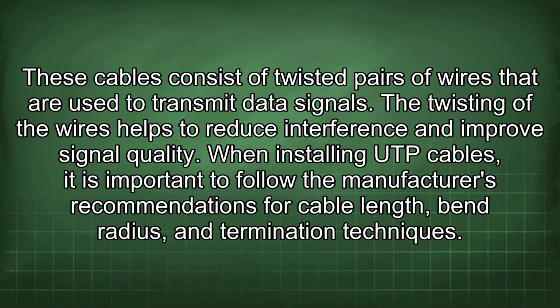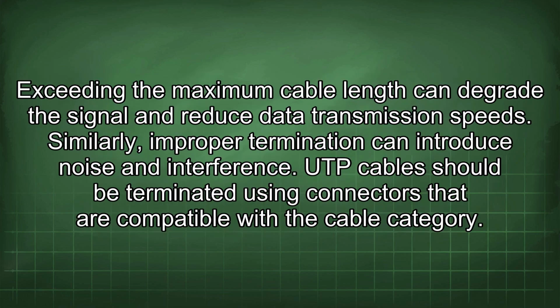When installing UTP cables, it is important to follow the manufacturer's recommendations for cable length, bend radius, and termination techniques. Exceeding the maximum cable length can degrade the signal and reduce data transmission speeds. Similarly, improper termination can introduce noise and interference.